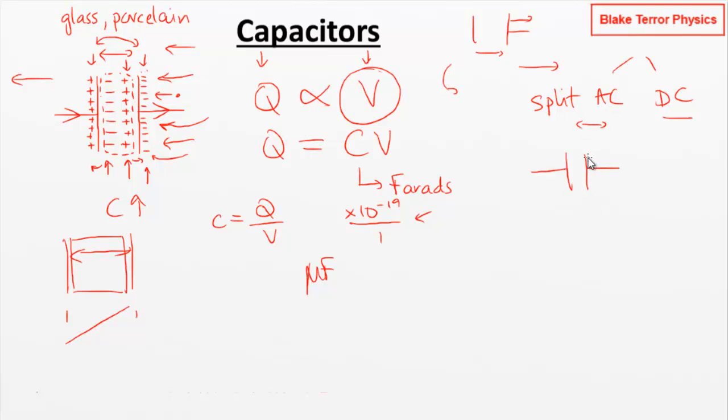So if you've started building up electrons on the right hand plate, it won't be long before the current changes direction and they'll all be off again. So the AC will keep on flowing because it's just going backwards and forwards, it's oscillating, but the DC will end up getting blocked. So it can be useful for that in certain more advanced circumstances.